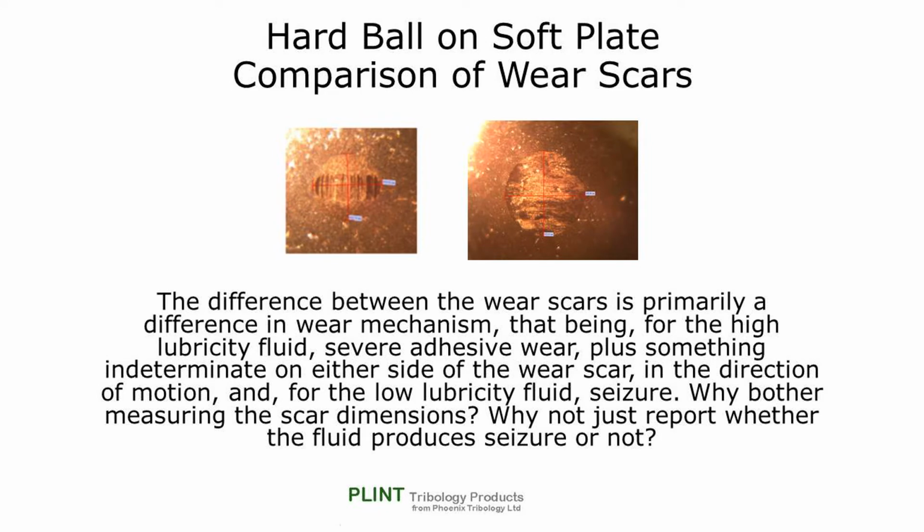The difference between the wear scars appears primarily to be a difference of wear mechanism, that being for the high lubricity fluid, severe adhesive wear, plus something indeterminate on either side of the wear scar in the direction of motion, and for the low lubricity fluid, seizure. Why bother measuring the scar dimensions? Why not just report whether the fluid produces seizure or not?